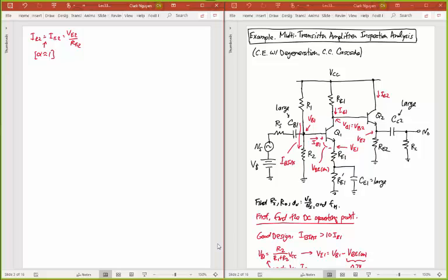So just some remarks on the procedure that I just went through. When you're doing this DC analysis, remember current is generated by a voltage across a resistance. That's going to be universal. When you get to 140 and you have to look at a much more difficult circuit with a lot more transistors, and you want to know how that's biased up, what you look for is a resistor.